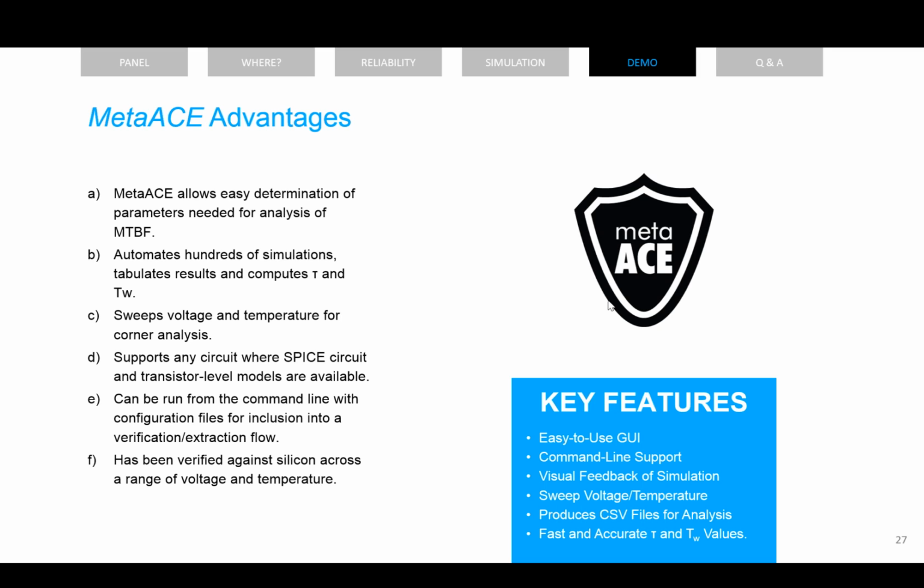So just to recap the advantages of MetaACE, it can easily determine tau and TW for you based on running simulations that accurately reflect actual circuit behavior. It can sweep voltage and temperature for you, and supports any circuit that you have a SPICE netlist for. You can run it from the command line. It's also been verified against silicon with work we did with Technion several years ago. There's a paper on that we can refer you to if interested.